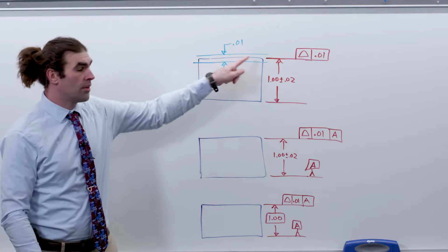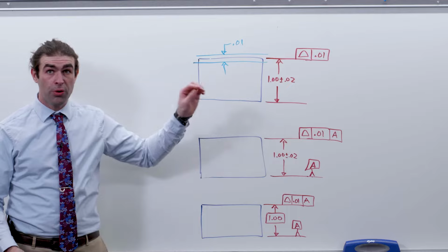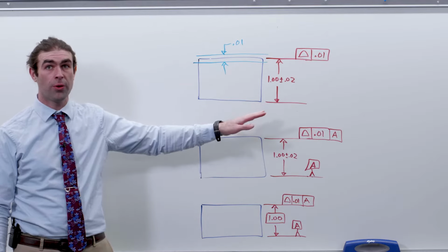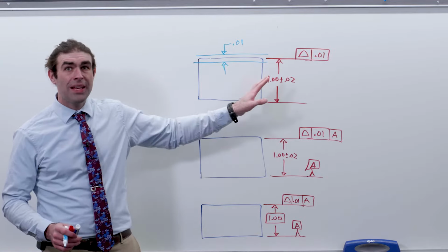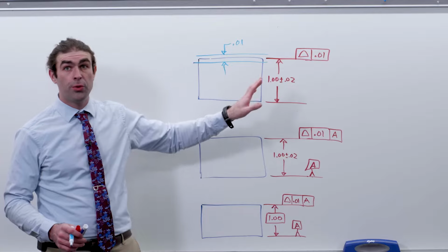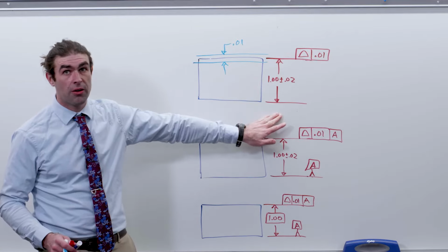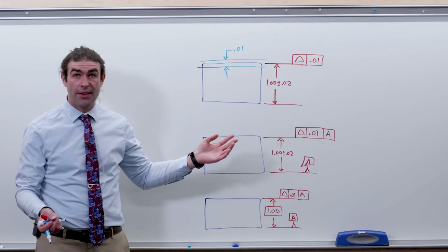Now, this zone must lie within the larger limits of size, so this profile does not control location. The limits of size control location. Now, it would be incorrect to use a basic dimension with this because there's no datum right here. So that's using profile as flatness.